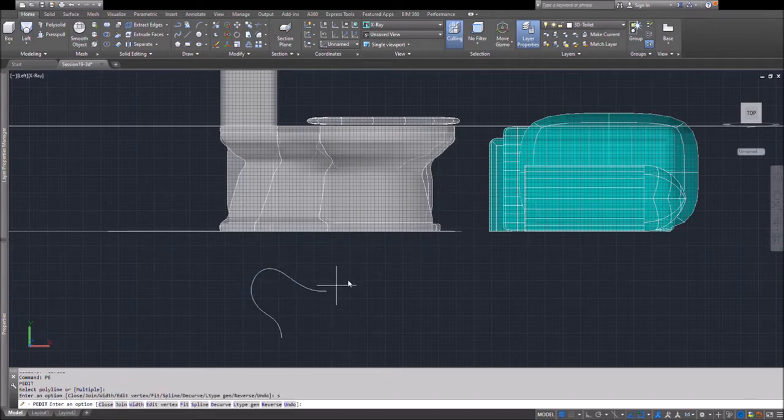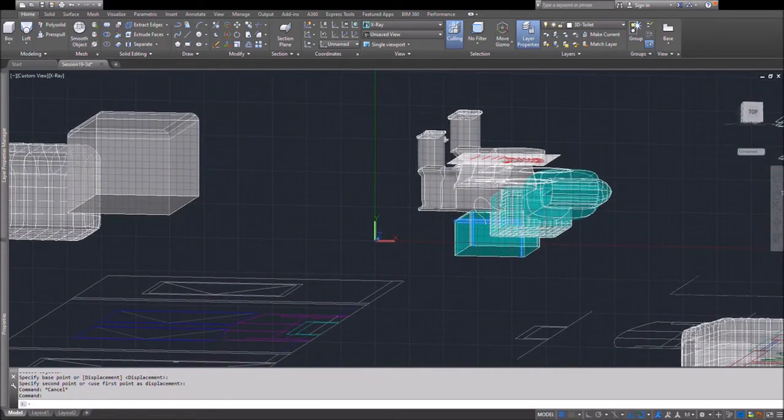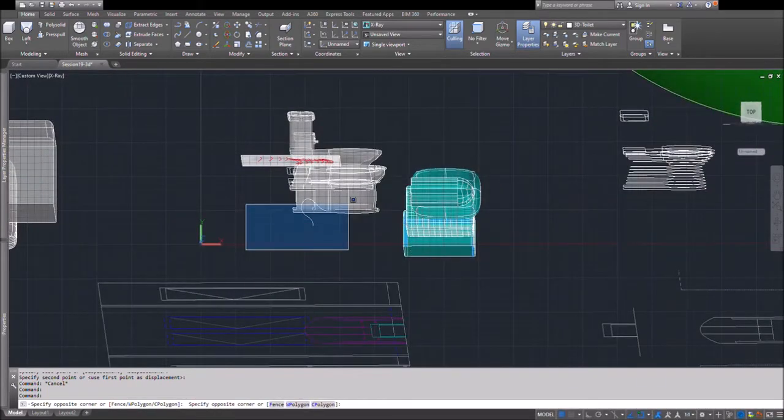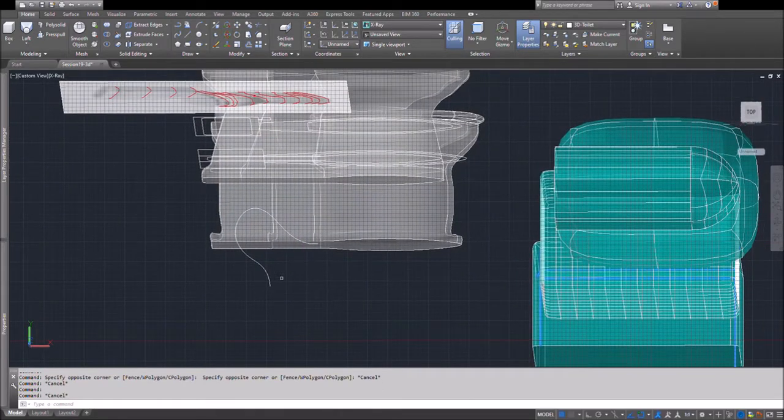And I'm just drawing it with a bunch of P-lines, and then I take the P-line and create a spline with it, or a curve, right? Because the trap is not made out of segmented pieces. It is a smooth curve, although if it wasn't smooth, then obviously things would get trapped in there, right? So that's the profile of what that is.